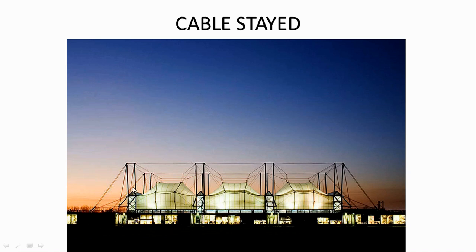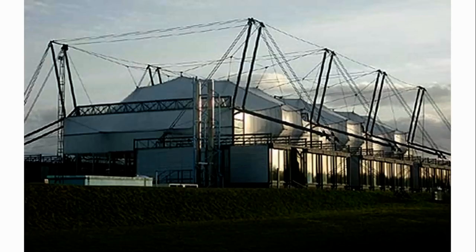But can you see what's going on here? There's actually 1, 2, 3, 4 what you might otherwise think of as cable-stayed bridges, a series of cable-stayed bridges. So you've got masts in pure tension, pure compression, pure tension, pure compression, and these masts are carrying the fabric to create the climatic envelope. Very beautiful structure. There it is again.